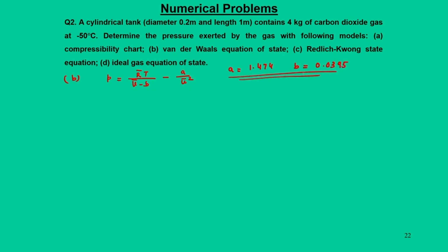These two we have to find from the data in the thermodynamic book for CO, and V bar is already calculated as 0.22 meter cube per kilomole. So, we all know this number, and then by inserting these values we can calculate P is equal to 72 bar. So, the van der Waals model gives us pressure to be 72 bar.